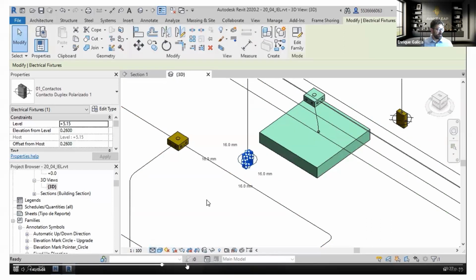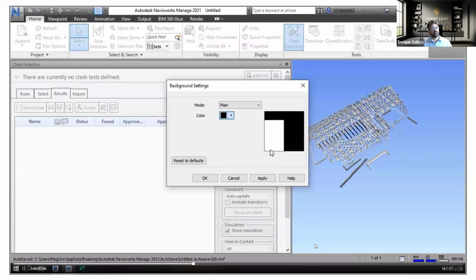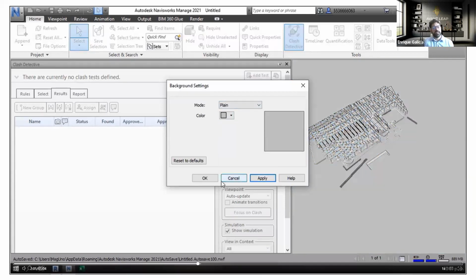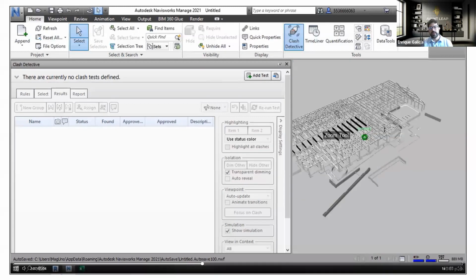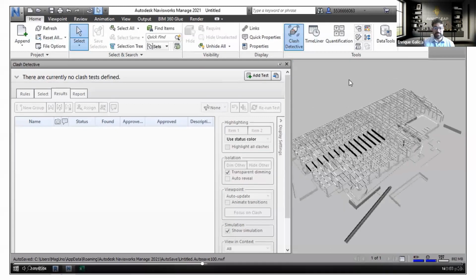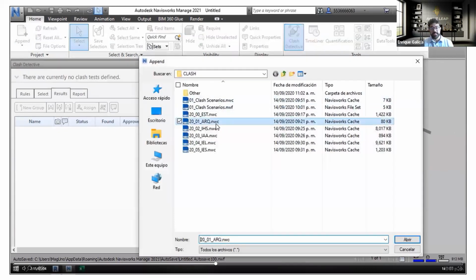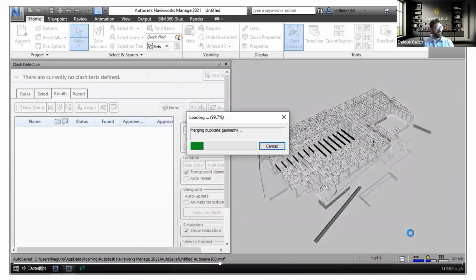So let's go into a little detail about it. Going into Navisworks, if we want to review it properly, we need to have elements changed in color and elements having their own sets, so that we know we're checking these structural objects, and elements that are already MEPs, conduits, or for sanitary installations.